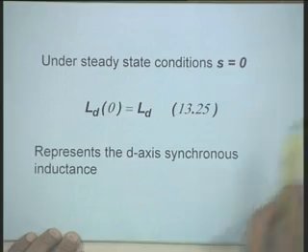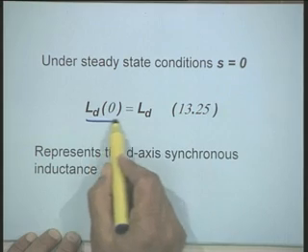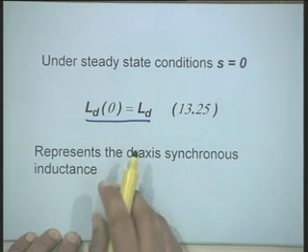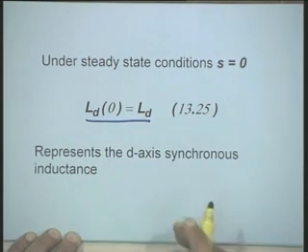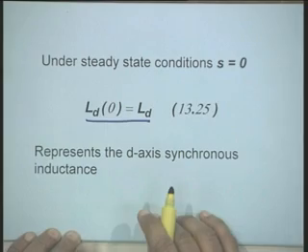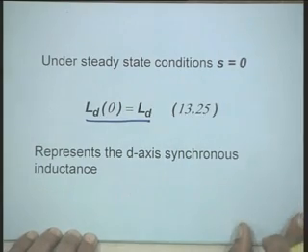Therefore, now I can say that under steady state conditions S is 0, and therefore LD0, that is the operational impedance for S equal to 0, is the same as the synchronous inductance or D axis synchronous inductance. Now, consider another case, let us say S is approaching infinity, a very high frequency transient.